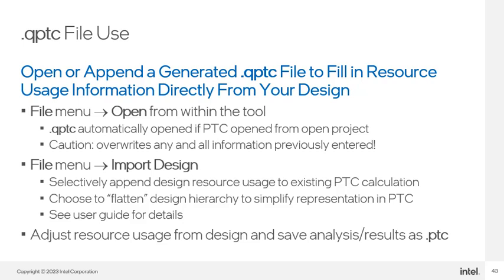Once you've opened or appended the .qptc file, you can manually add to or adjust any of the imported resource usage information. Whether you adjust the .qptc information or not, save the PTC settings and analysis as a new .ptc file for future use.